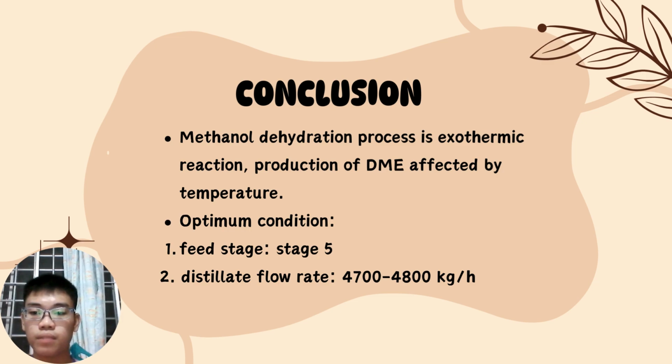From this study, the optimal condition for the production of DME is when the feed stage of the RadFrac is intermediate, which is around stage 5, and also when the distillate rate is around 4,700 to 4,800 kg per hour.